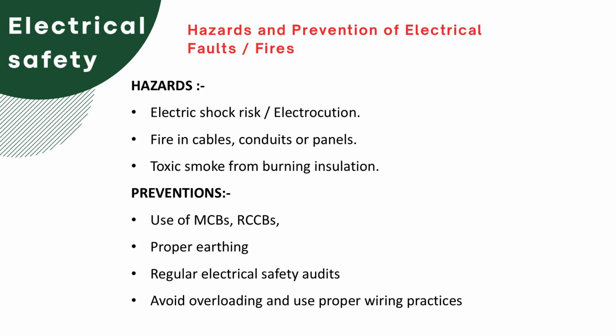Now, next one is avoid overloading and use proper wiring practices. So this one is for you, that you should not connect many circuits to a single MCB, a single circuit breaker, and you use proper wiring practice. So these are the preventions and hazards of electrical faults.